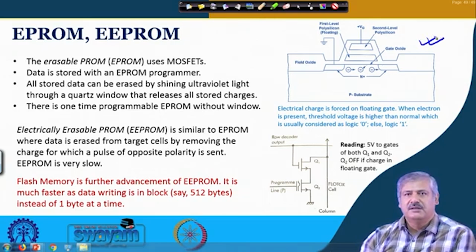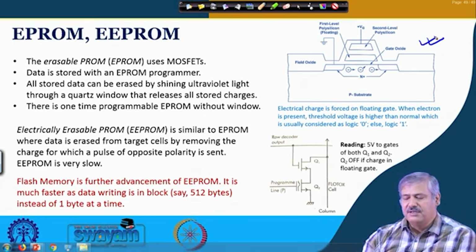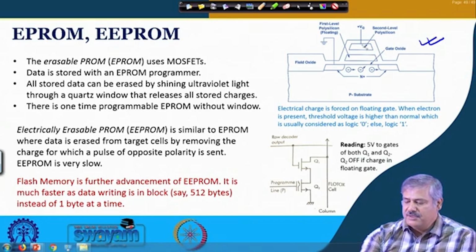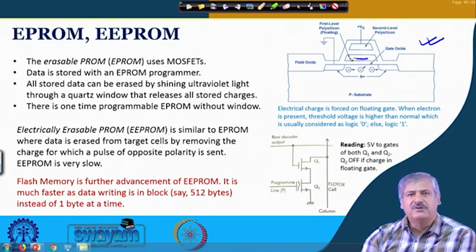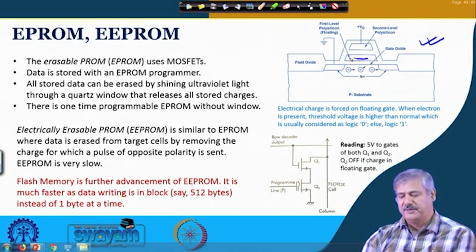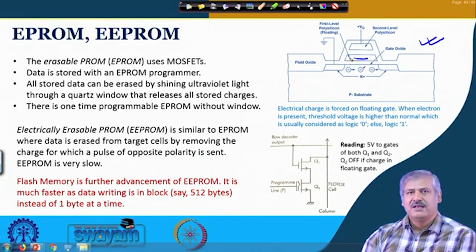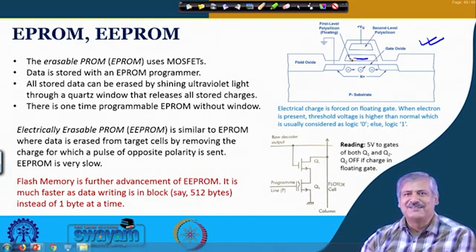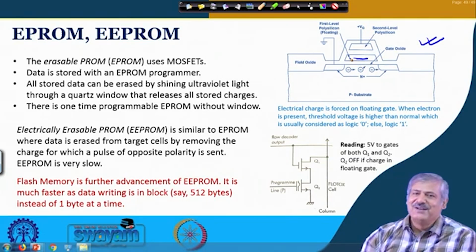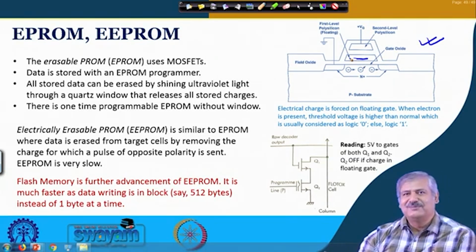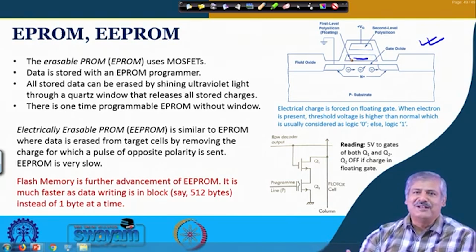So, in the MOSFET based realization of this memory cell, there is a normal standard MOSFET gate side, but here there is an additional gate called a floating gate put over here. Okay. And by a particular phenomenon, when the appropriate physics works out, tunneling etc., we will not go into the details of that.